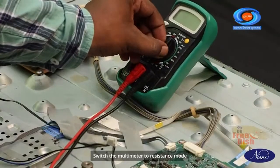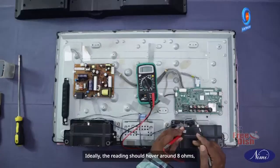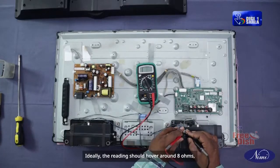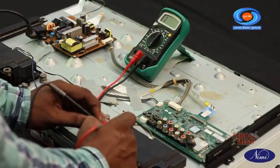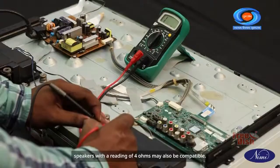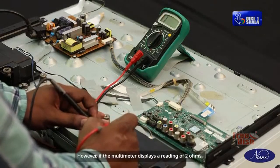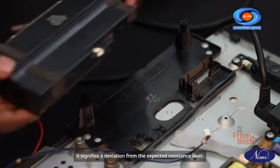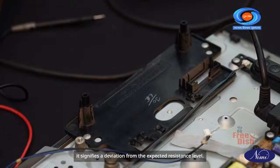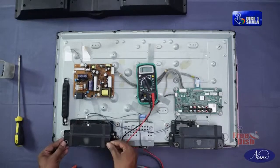Switch the multimeter to resistance mode and focus on testing the left speaker. Ideally, the reading should hover around 8 ohms, specifically tailored for this speaker model. In some instances, speakers with a reading of 4 ohms may also be compatible. However, if the multimeter displays a reading of 2 ohms, it signifies a deviation from the expected resistance level, indicating a need for speaker replacement.